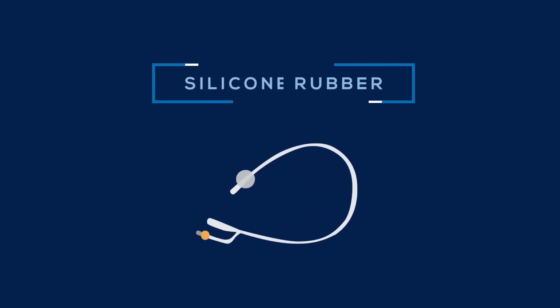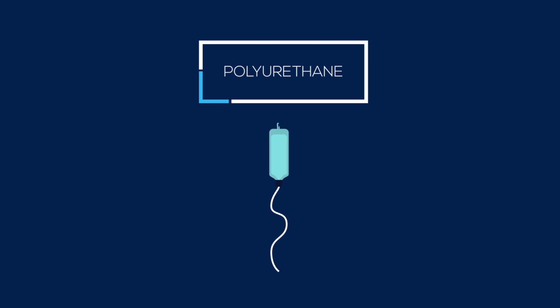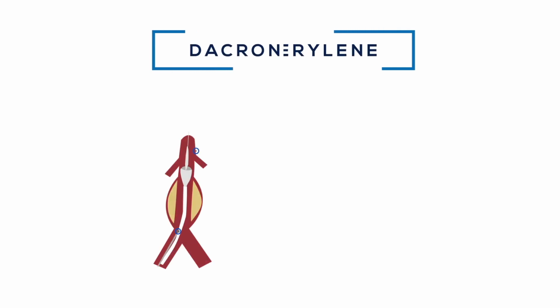Beginning with soft materials, medical-grade silicone is widely used for its low cost and ease of manufacture. Silicone catheters, tubing, balloons and implants can be easily moulded to different hardness grades and shapes. Polyurethane is another soft, flexible material which is widely used for catheters, balloons and extrusions.